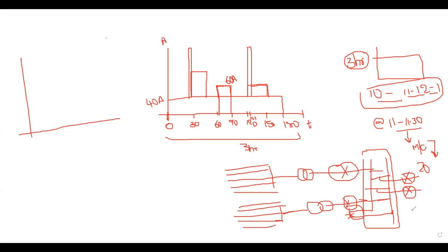So for this master trip energization and everything, we require some DC load, right? I am considering that my continuous load is this, and my protection was operated at the 60th minute and it exists for 1 minute. After that, I found it is a normal thing, so I closed the breaker. That is again one. And finally, I am taking the same operation again: the busbar differential protection operated again at the end of the cycle.